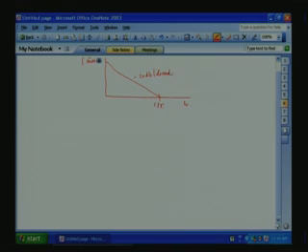So, according to control system this is good, but let us take the phase margin. This will always give a fixed 90-degree phase shift to the signal. So, if the plant has some other frequency dependent element and we again give a minus 90 degree, so minus 90 plus minus 90 it will be minus 180.